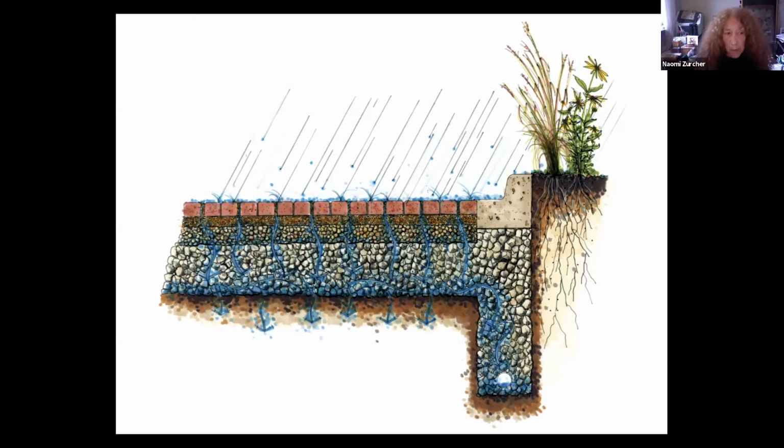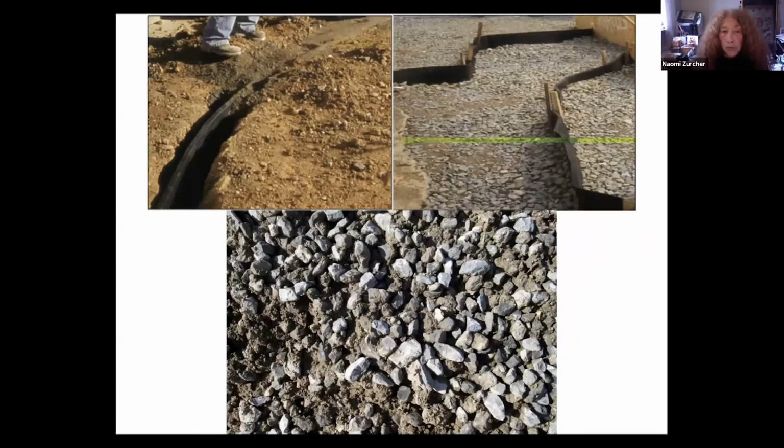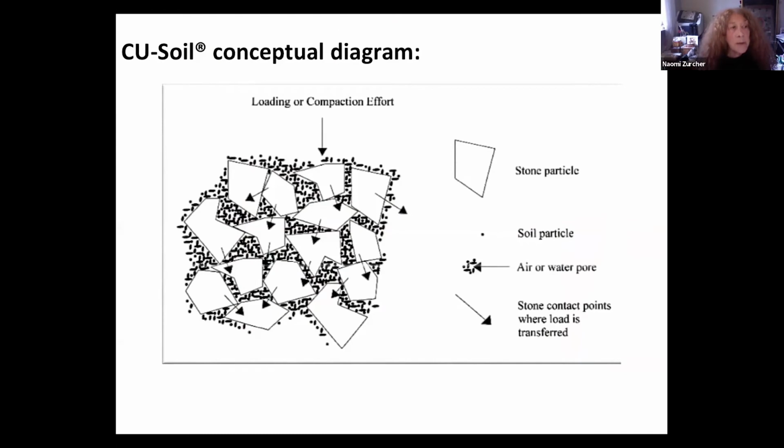To mitigate this drawback, these pavers can be combined with opening covered soil designs, root paths, plus root-friendly material such as structural soil. Structural soils are based on a stone matrix, which will, when compacted to the load-bearing protocol, form a matrix which has enough soil and voids as to accommodate gas exchange and moisture retention within the mixture, supporting tree root growth and communal root exploration.